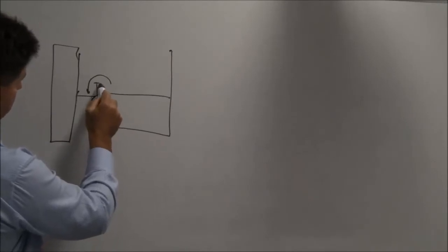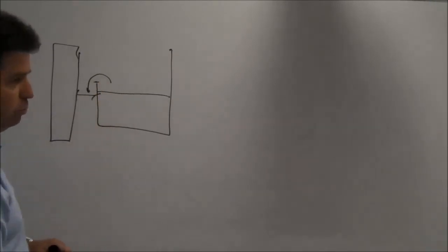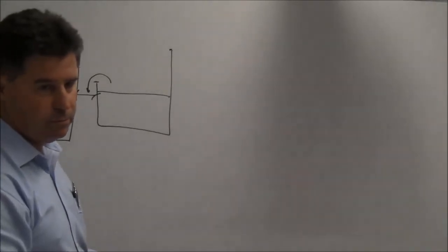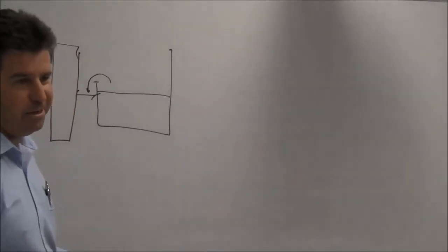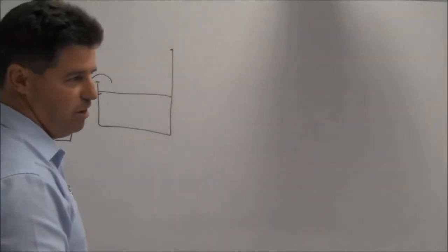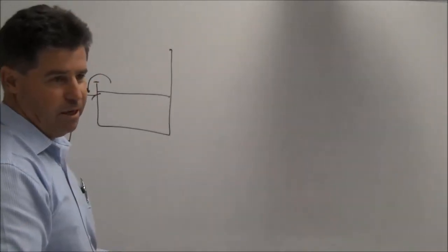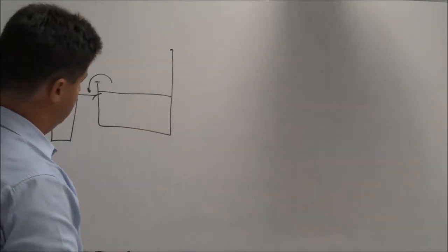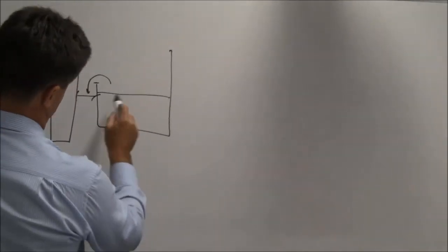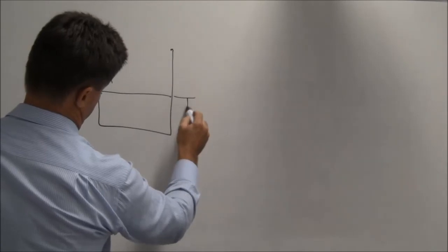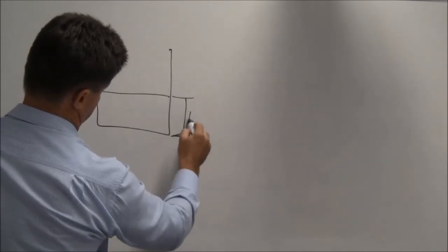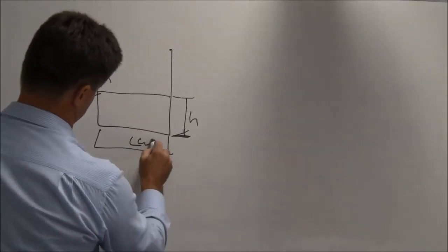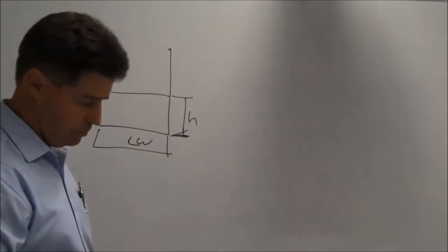We want to make sure that when it's working normally, it's not overflowing. We don't want people coming back and saying the whole thing's overflowing every time it rains, under normal conditions. So the square millimetres will be below the line. The gutter capacity in square millimetres will be whatever that height is by whatever that width is. Sure, no problems.